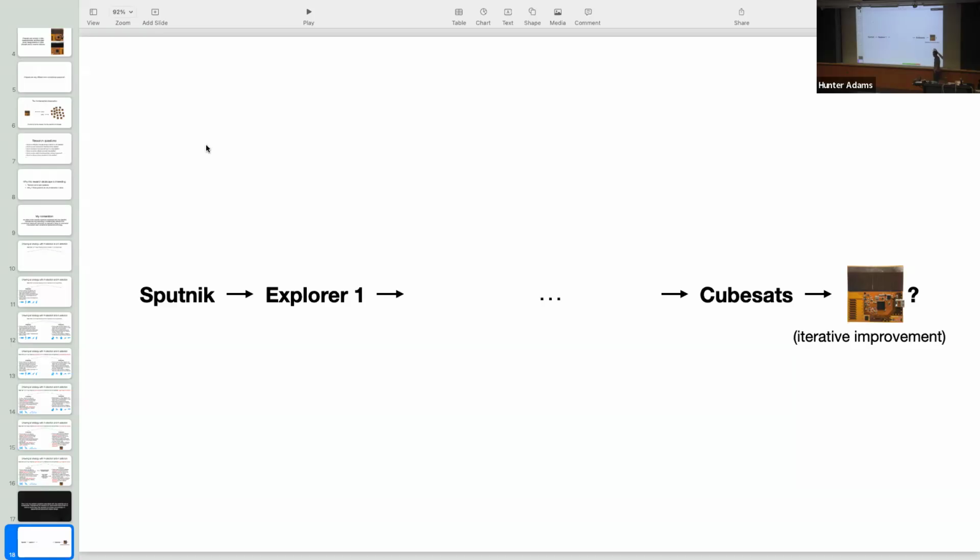I think this suggests two things that are a little bit incorrect. I think it suggests, first of all, that an individual chipsat is useful, which is not. Like I said, it's the collective that's useful. And furthermore, it suggests that the fundamental innovation here is in a reduction of mass. I don't think that's true either. I think the innovation is not in a reduction of mass, because in order to do something useful in space with these things, you need to launch so many of them that the swarm mass is perhaps approximately the same as a single conventional satellite's mass. So I think the innovation is not a reduction of mass, but instead a fractionation of it.